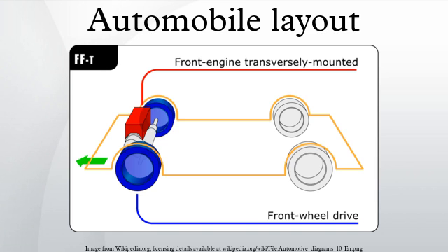While these aids do tame front-end plow, cars fitted with these systems are still at a disadvantage when track-tested against rear-wheel drive vehicles. Torque steer is the tendency for some front-wheel drive cars to pull to the left or right under hard acceleration. It is a result of the offset between the point about which the wheel steers and the centroid of its contact patch. The tractive force acts through the centroid of the contact patch, and the offset of the steering point means that a turning moment about the axis of steering is generated. In an ideal situation, the left and right wheels would generate equal and opposite moments, cancelling each other out. However, in reality, this is less likely to happen.